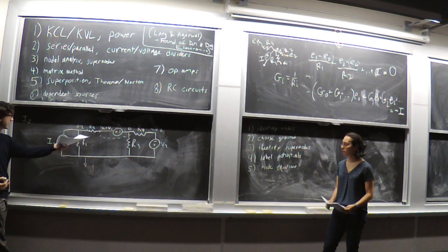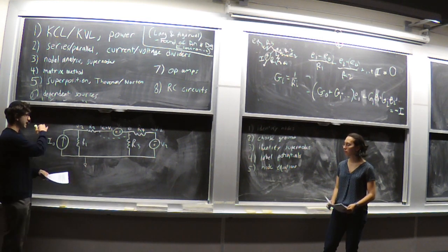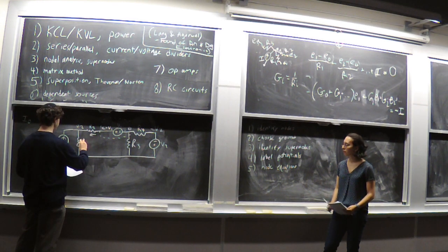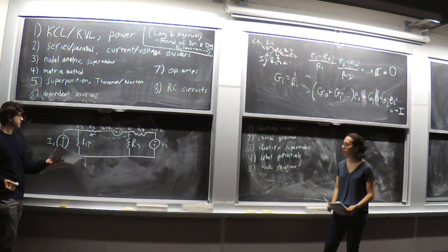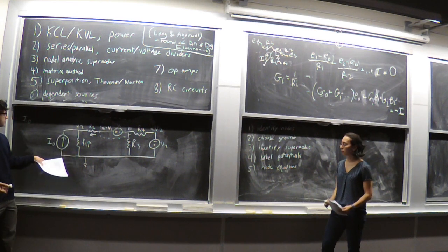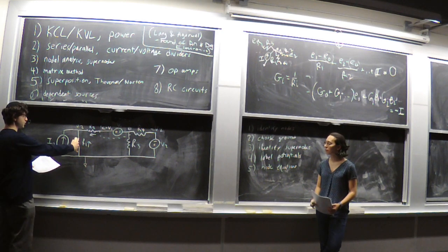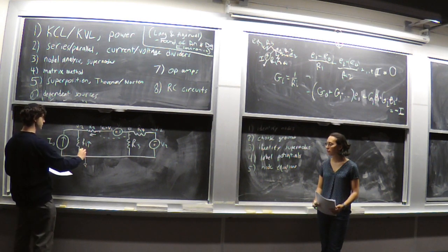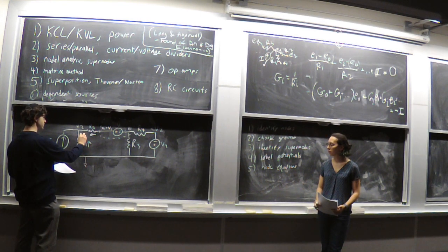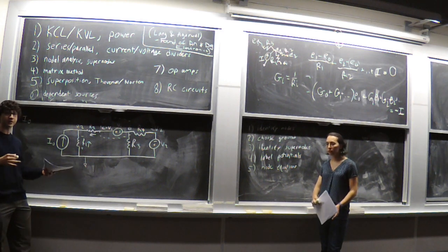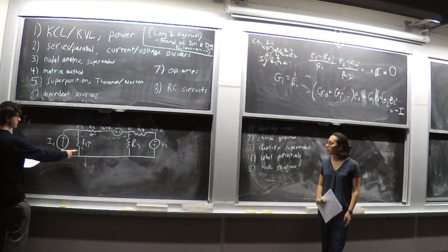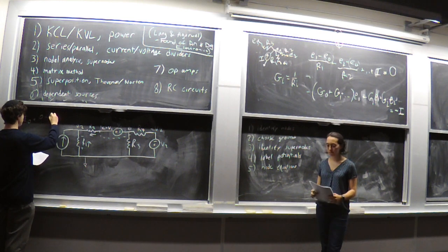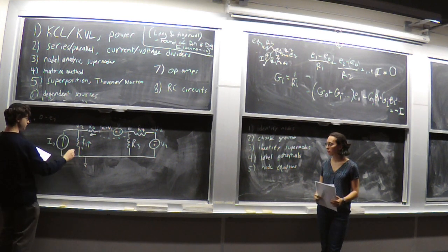So now, when I look at these two branches and figure out what current I'm going to be adding onto this equation, I have to view it in the direction going into the node. So I'm going to be going like that. And as Hannah was saying earlier, what is the current going through this resistor R1? Well, it's going to be the voltage drop across R1 divided by the resistance R1. And as we were talking about before, because the current's going this way, we kind of have to view the positive side of the resistor over here and the negative side over there, so that we have our directionality in check. And so this side is at ground, so that's going to be 0. This side is at E2, so 0 minus E2 is now the positive voltage drop across R1.